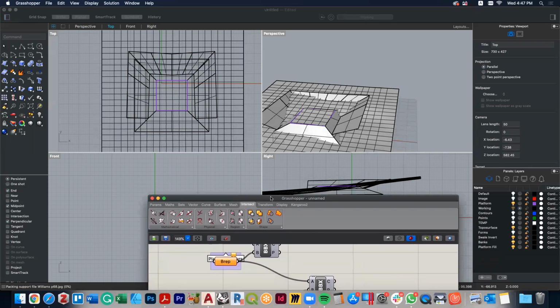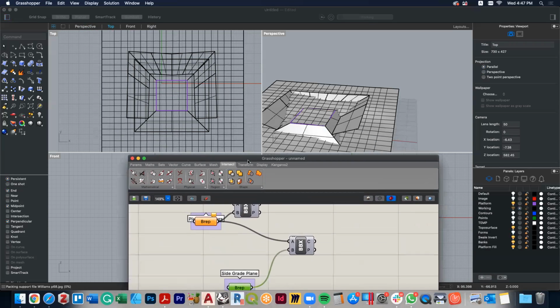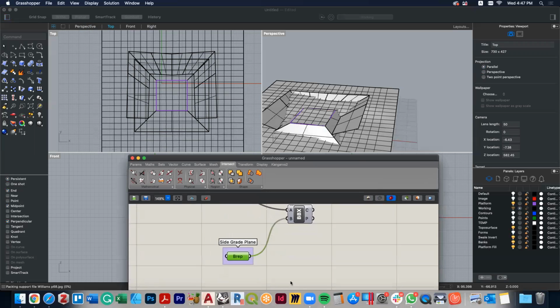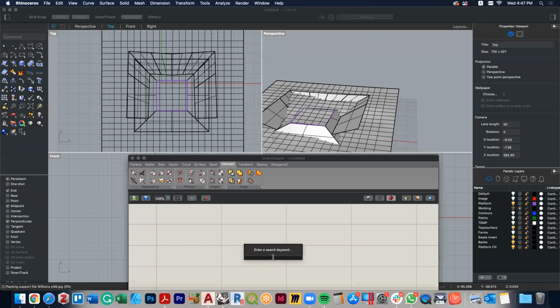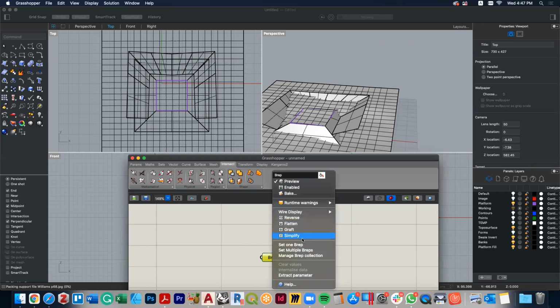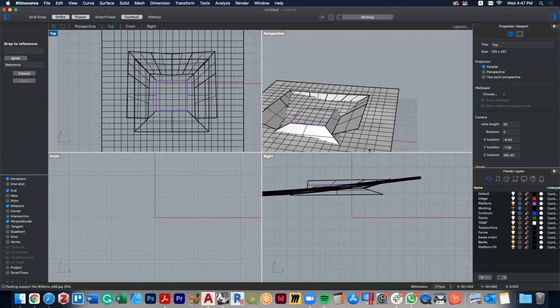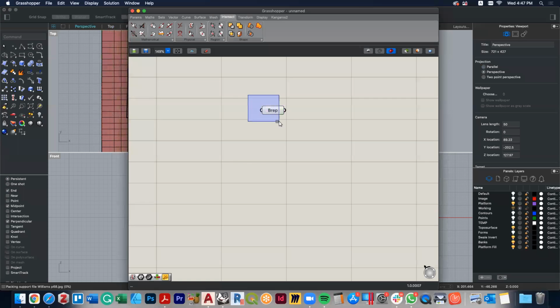And so we're going to use a bit of Grasshopper again. I hope you don't mind. This time we're also going to create a B-rep. And with the B-rep, we're going to set one B-rep, set that one there, group it and call it topo surface.